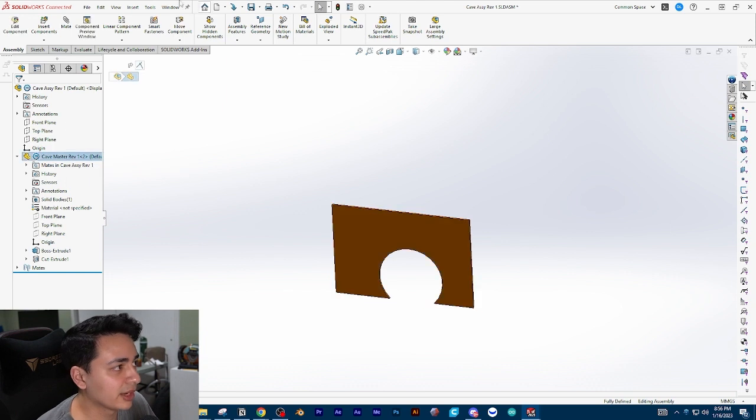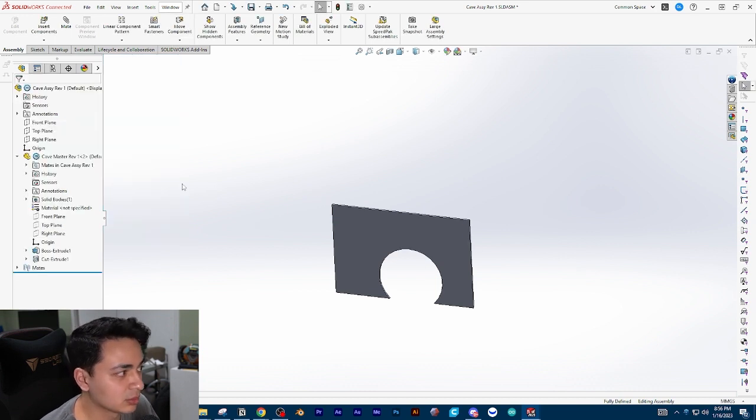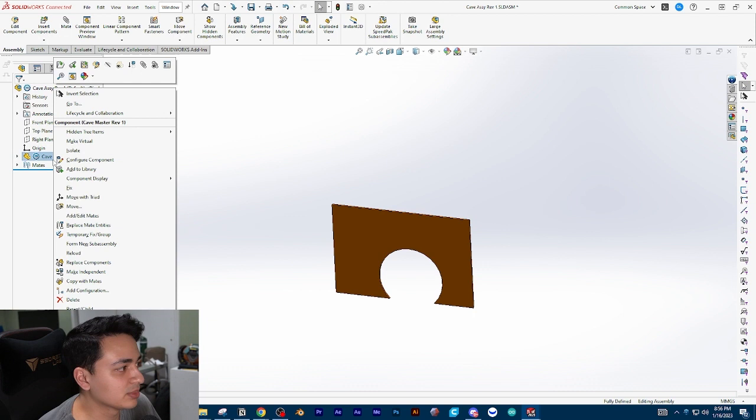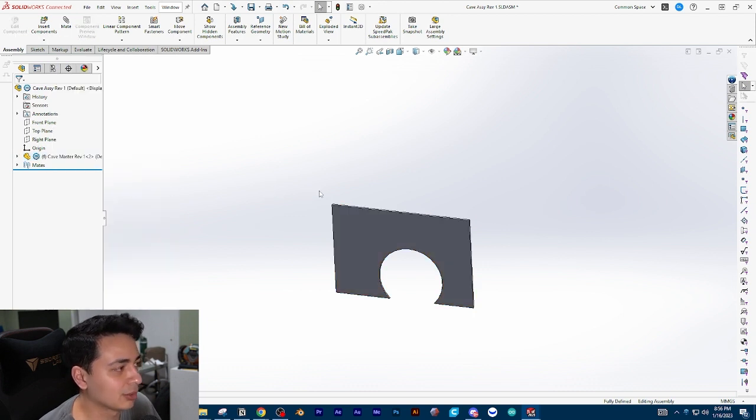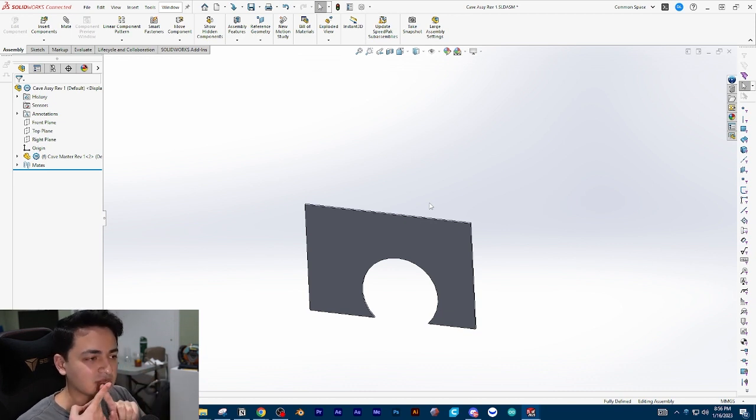So now this thing, no matter what I do, won't move. I can't move this, and it's aligned to 3D space where we want it. All right, so that's good. For extra measure, sometimes I'll go back and fix it just so I know it won't move anywhere. So the reason we're doing this is we have our ultrasonic sensor, and we're going to have an Arduino, some lights, and the servo motor. So I want a general idea of the overall size of my components and where they're going to go. And we're going to plan all of that in this file.